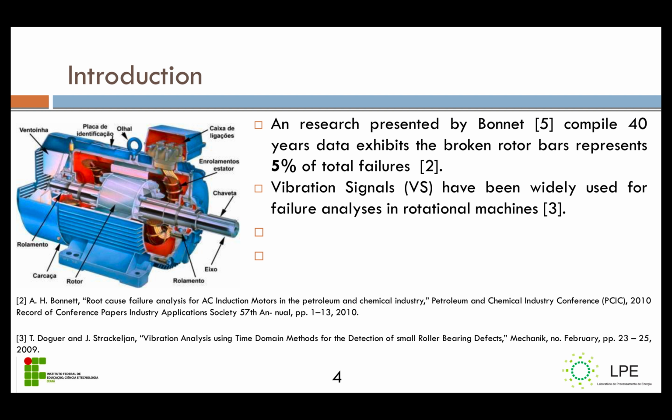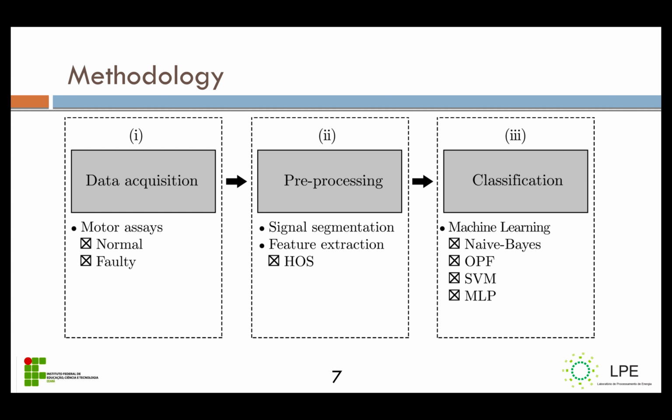Our methodology consists of 3 major steps: a data acquisition, where we simulated the induction motor in 2 basic conditions, normal and faulty. Then, in a pre-processing phase, we conducted signal segmentation and feature extraction using higher-order statistics, and we performed classification via machine learning methods, specifically naive Bayes, OPF, SVM and MLP.